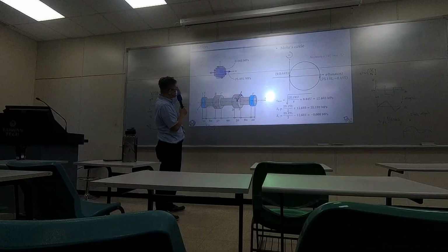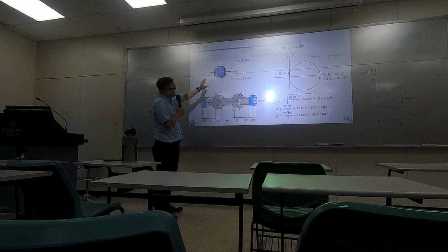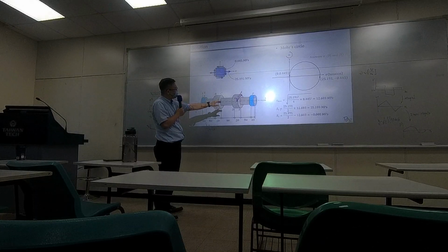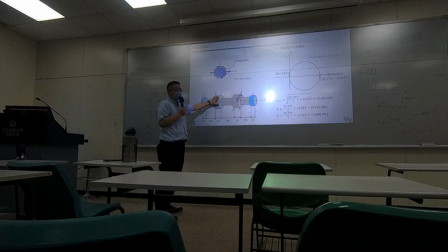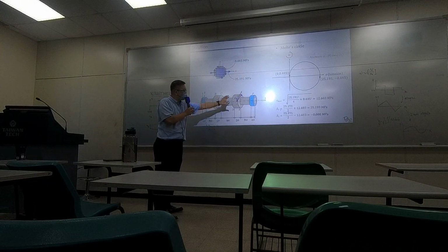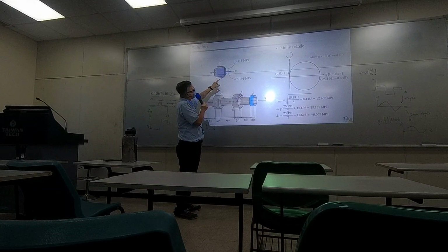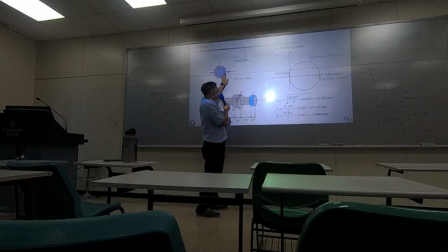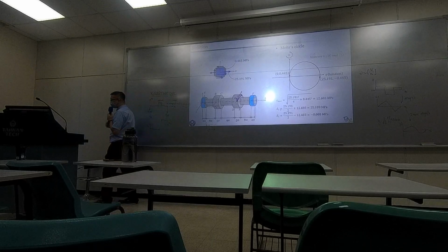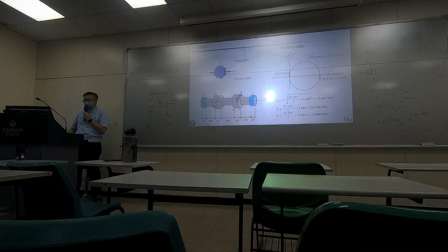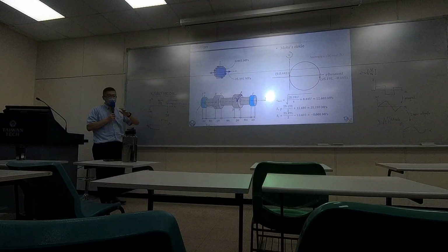I'm not sure if I made the drawing right or not. Here or there, somewhere. So anyway, position-wise, don't worry too much. But if you ignore the geometry of the pulley and just treat the whole thing as a cylinder, at one position it's carrying the largest normal stress and shearing stress. You can draw a Mohr circle for it, and then you can compute the principal stresses and the maximum shear stress. Okay, so that's the goal for the entire beam problem.